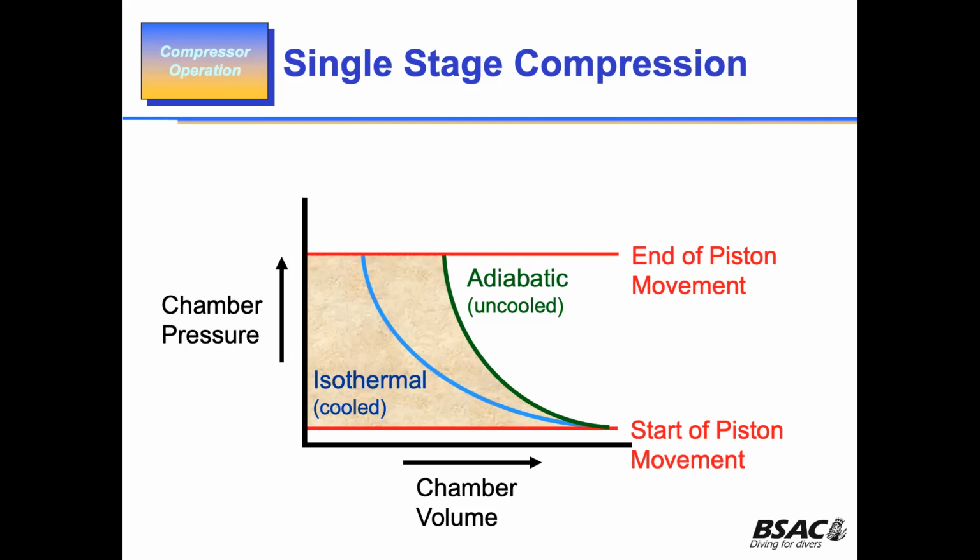If you could see the curve for the best possible and then add the curve for isothermal, it's a lot closer to the better compression. So we try to get isothermal, and we try to stick to an isothermal gradient. It doesn't always work because, as I said, all compressors really are adiabatic in their action.